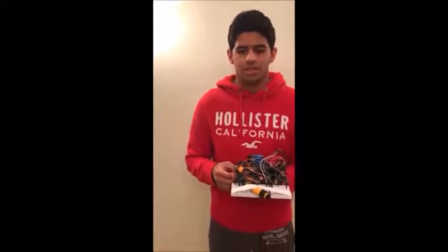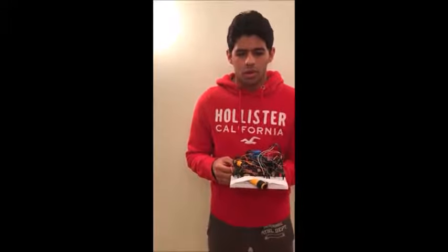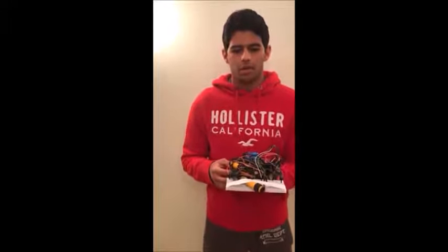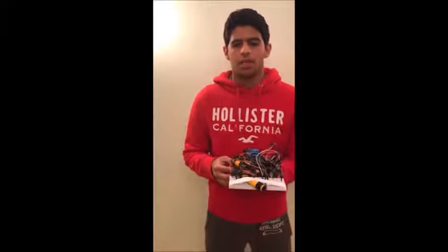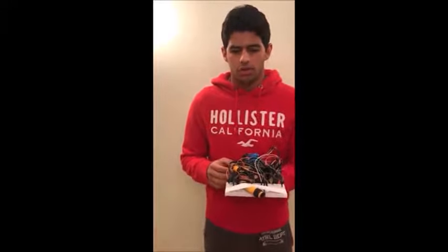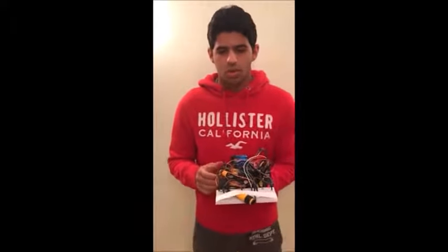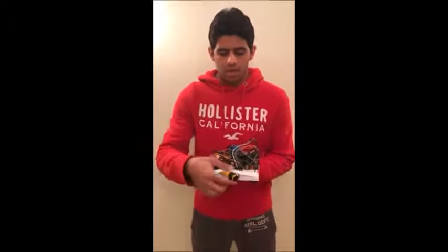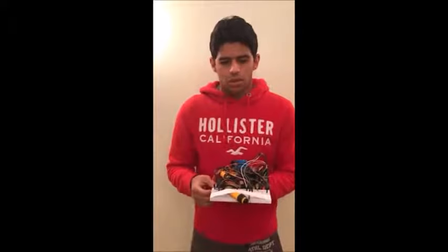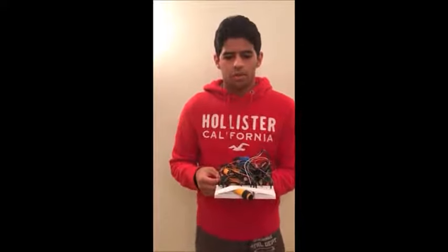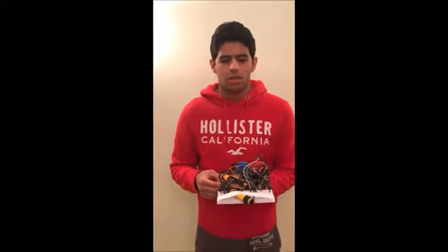This works by sending a digital signal, either a 0 or a 1, with 1 meaning that the door is open and 0 means it is closed. If the signal is 1, all of the other functionalities will be disabled and the car will not move. If the signal is 0, the car will run normally. The second IR sensor is placed on the front side to detect obstacles that the car should avoid.